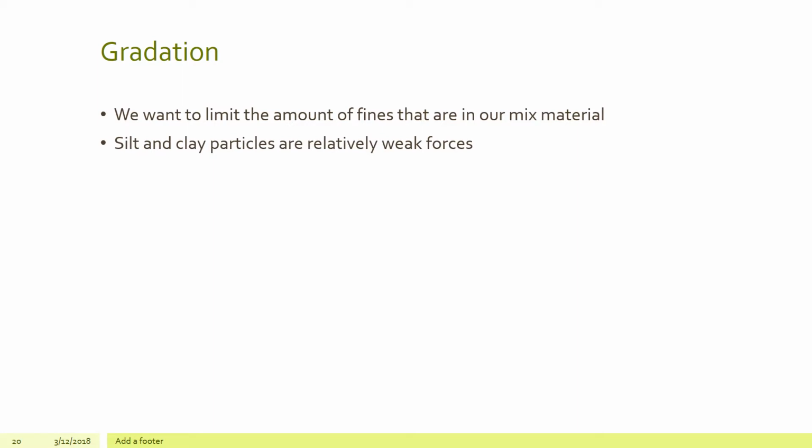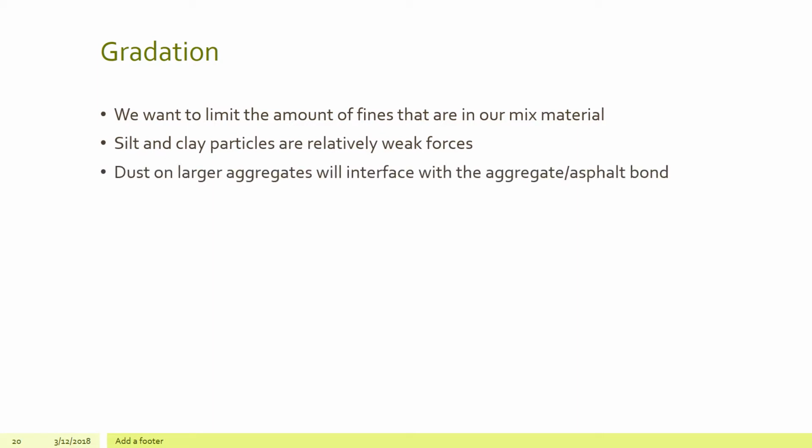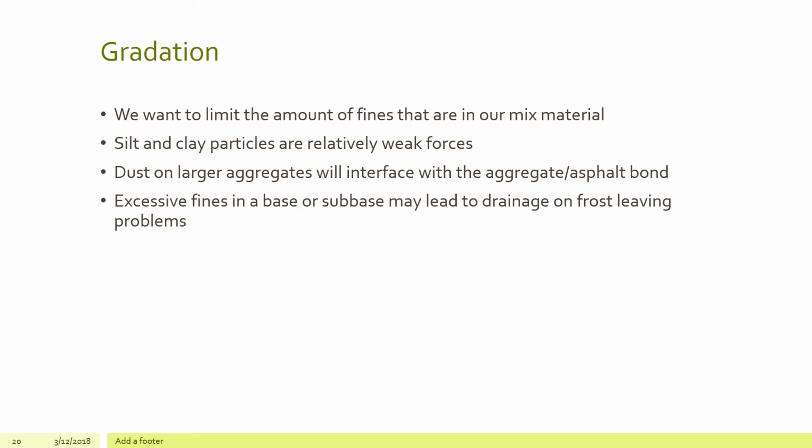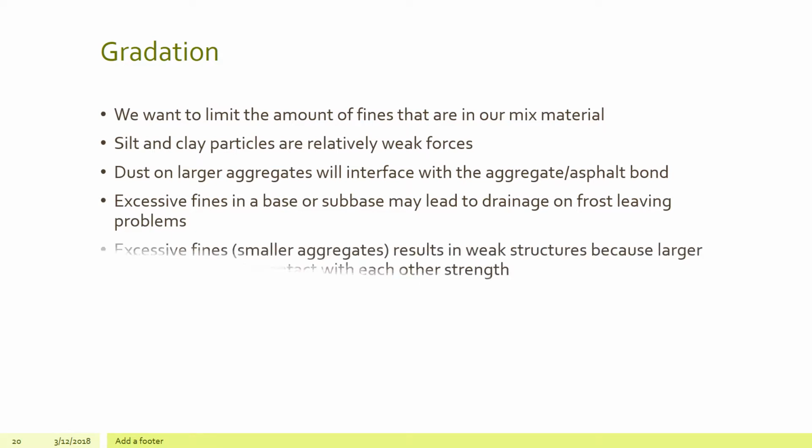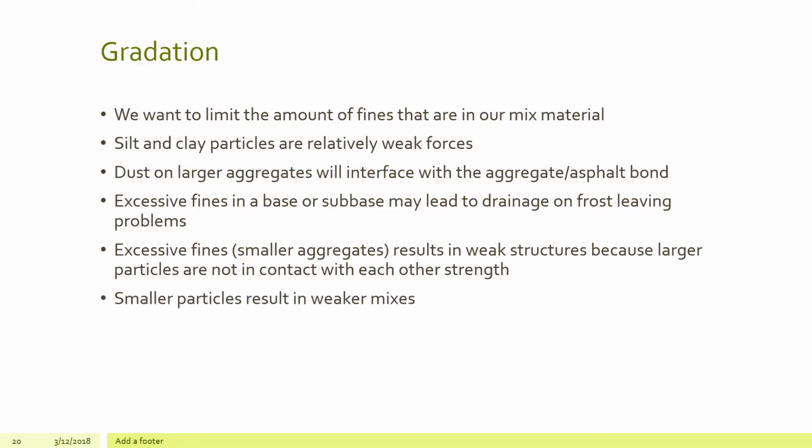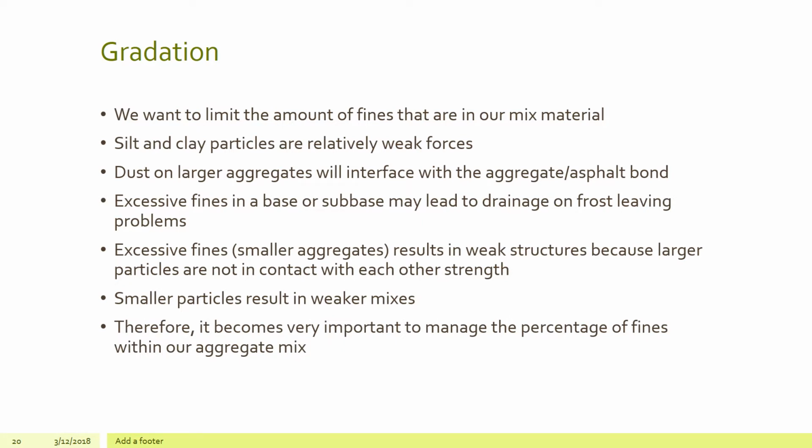Other factors that we want to consider with gradation: we want to limit the amount of fines that are in our mixed material. Silt and clay particles are relatively weak forces that we're going to deal with. Dust on larger aggregates will interfere with the aggregate-asphalt bond that we have. Excessive fines in a base or sub-base may lead to drainage or frost heaving problems. Excessive fines, of course smaller aggregates, result in weak structures because larger particles are not in contact with each other. Of course, the strength is reduced. Smaller particles result in weaker mixes. Therefore, it becomes very important to manage the percentage of fines within our overall aggregate mix.